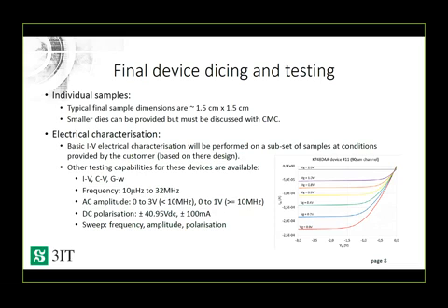We also have a test station that has really, really low current, like in the picoamps, if required. So we can use the machine that's needed to do basic electrical characterization of the device per se. We can vary frequency, amplitude, polarization. So really, the limitation here for basic electrical characterization is not the testing capability. I think it's more the time that we allocate for this sanity check to make sure that things are working properly, the contacts are good, before we send the device over.